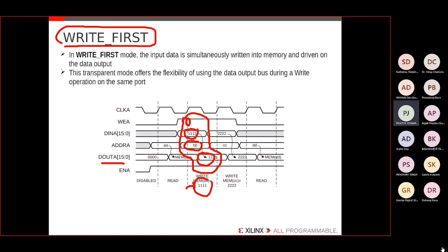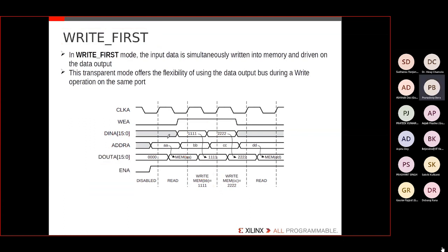Please sir, repeat it, sir. Yeah, because this is important. Okay. So the memory will be able to write whenever write enable is high, right? You can see here write enable is high at this point and write enable is high at this point. At the other points, it is only a read operation, here, here and here. So it is only reading.